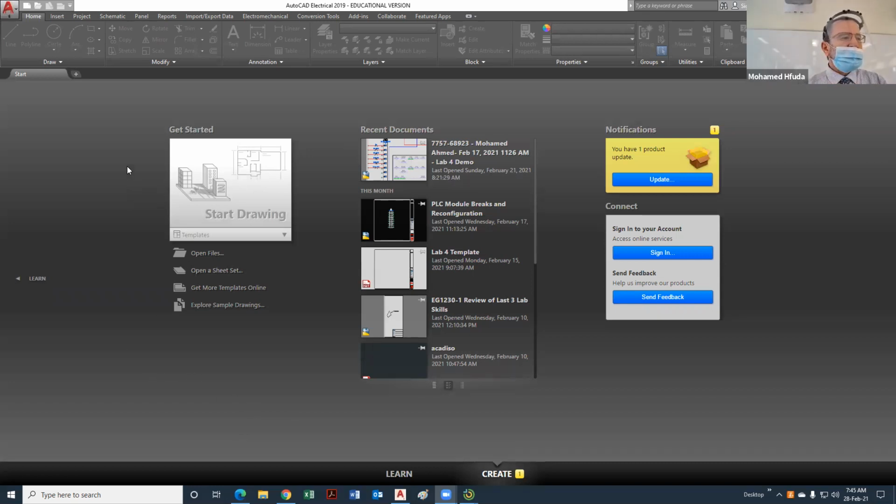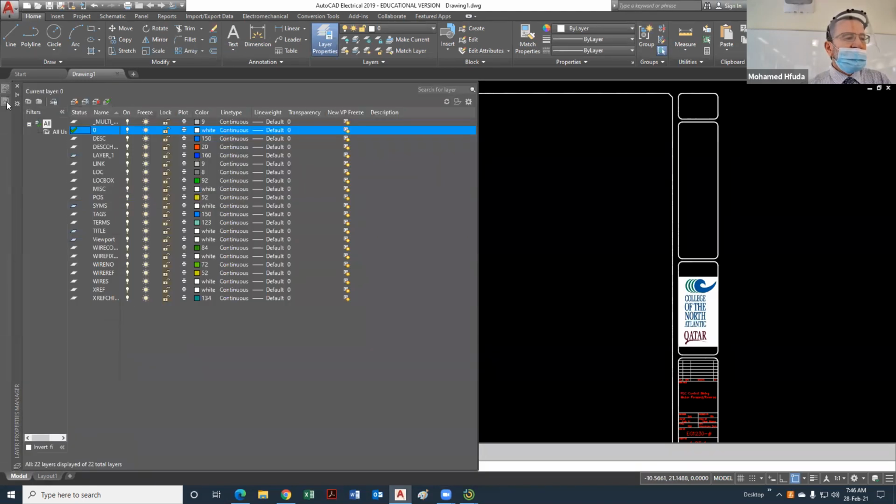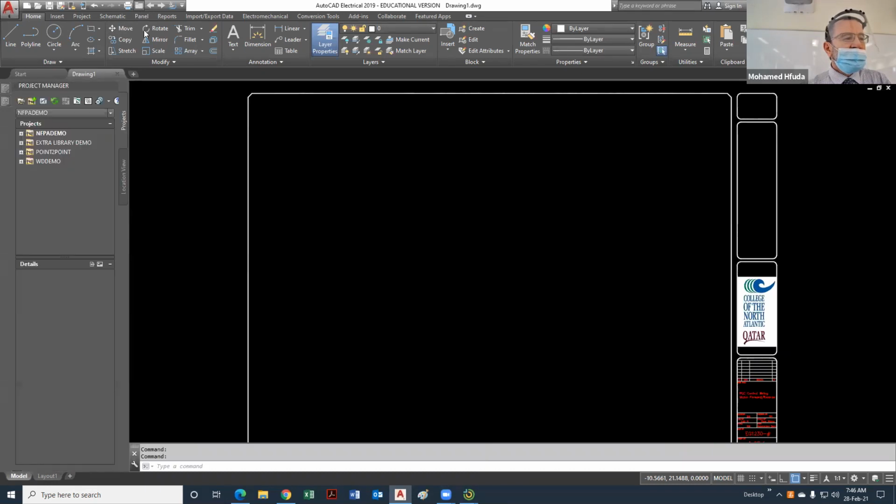All right, so bear in mind, if you don't see this, there's also a project tab, but you cannot have this project manager until you have at least one drawing active. So I'm going to just start a drawing, any drawing, it doesn't matter. And now, where's my project manager? It's not here, so I have to activate it. There it is. This is the project manager.